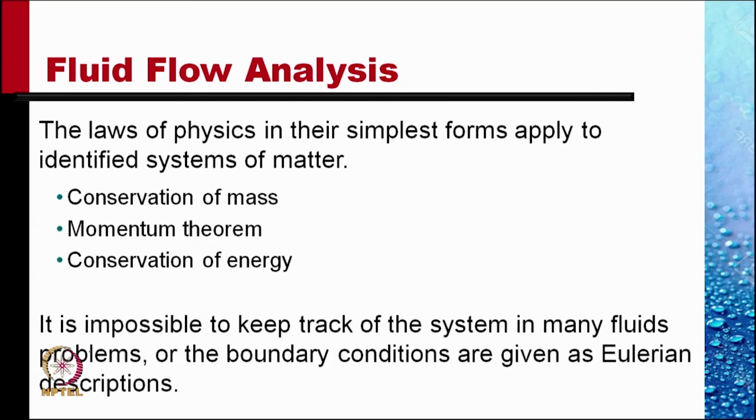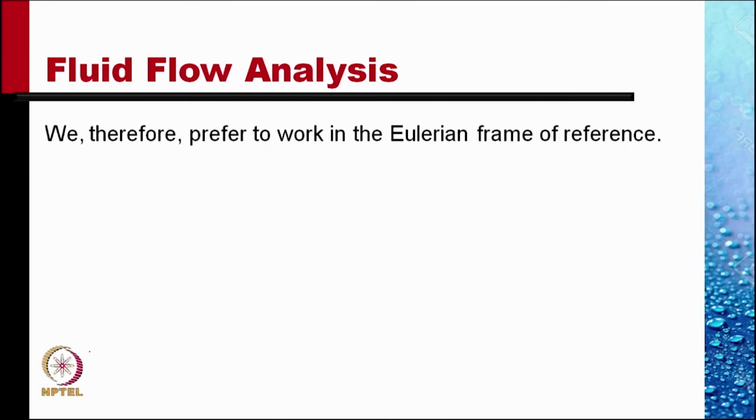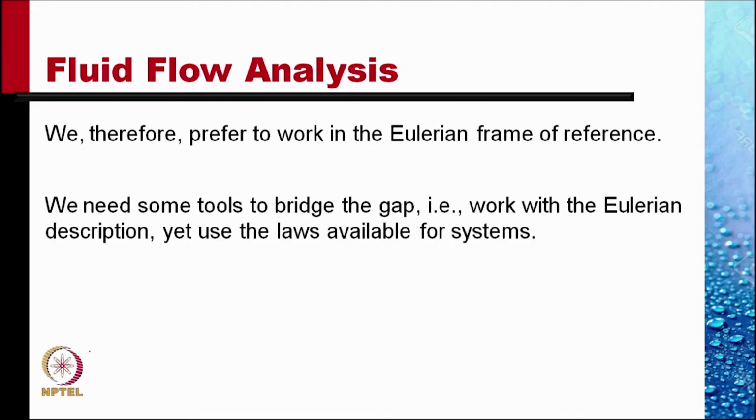So what do we do? It is impossible to keep track of the systems in many fluid problems, or the boundary conditions are given in Eulerian description. We therefore prefer to work in Eulerian frame of reference. The laws are available in the Lagrangian frame of reference, so we need some tools to bridge the gap, i.e. work with the Eulerian description yet use the laws available for systems or the Lagrangian description.